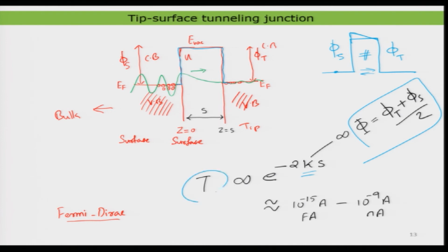So we need the tunneling, the transmission probability or the tunneling probability. Both names are used, for calculating the current. Yeah. And there is one more important thing that you need to understand at this point, which is known as the density of state. The density of state is defined by the number of levels that are available in a given energy.